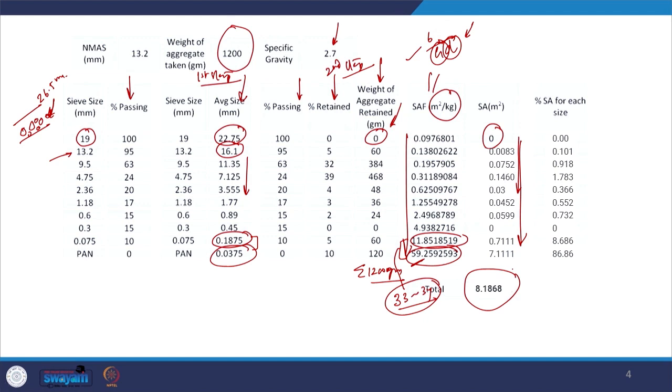on the distribution of surface area within the aggregate mixture, and in fact this distribution is very important in relation to the performance, in relation to the bitumen film thickness, because depending on the amount of fine aggregates, the more the amount of fine aggregates, the more will be the requirement of bitumen to produce a mixture with some standard range of film thickness. So, it becomes critical that way.